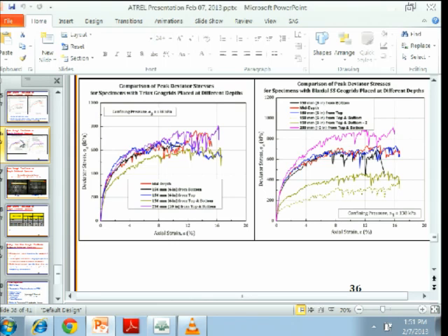So my point is that I'm not convinced by your data, and I could be wrong. It seems a little gray, and I don't know why I would pay extra money to put in geogrid. I'm not seeing the benefit here unless you have huge strain levels, and these are good aggregates. So why am I putting this in? This is just my comment. I don't know if there's an answer yet.